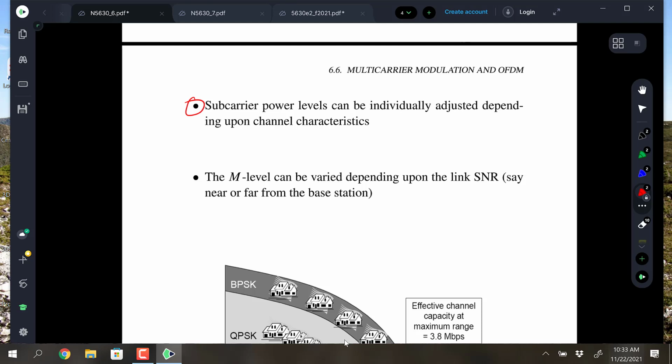A lot of what you're going to get to understanding this is going to be in the final project/exam. I have a nice exercise that you'll get to work with OFDM. It teaches you about the cyclic prefix and what are called, let's see, I'm going to forget the name, pilots. Yeah, pilots that you can send into the channels to estimate the channel. The pilot is just allowing certain carriers to be pilot carriers that help you learn the channel, and then you can unravel things with that too. Different standards use different pilots in the OFDM waveform, but that allows you to have the channel estimated, because a pilot will come straight through and contain only the channel distortion. You'll see that in action too.